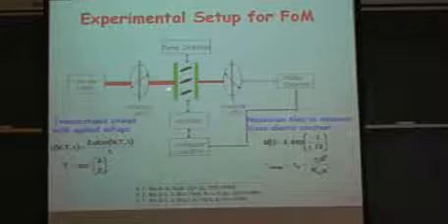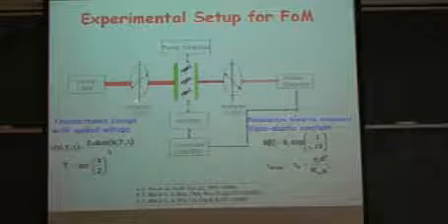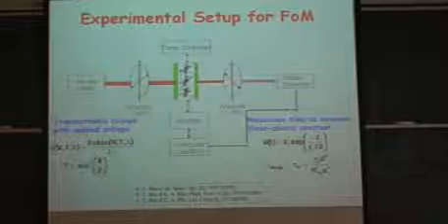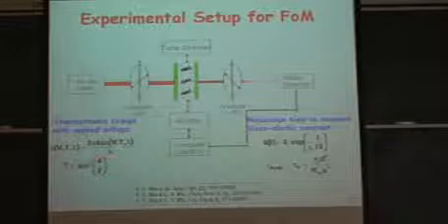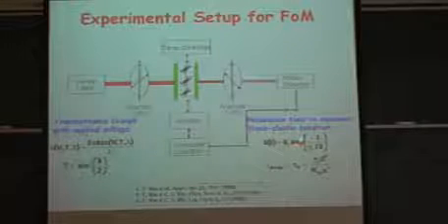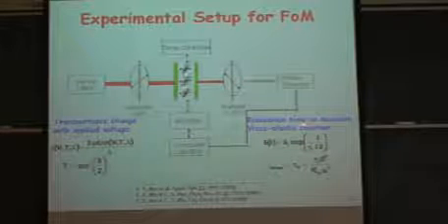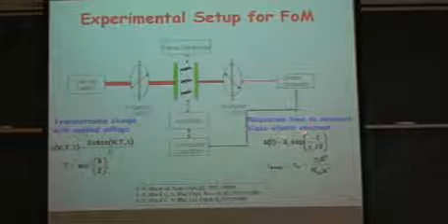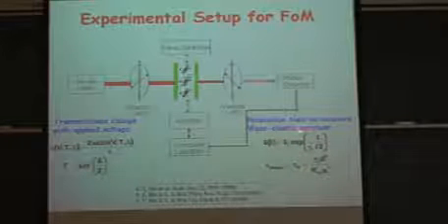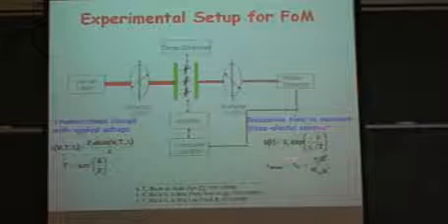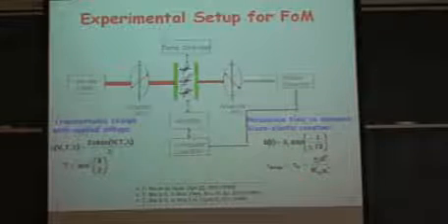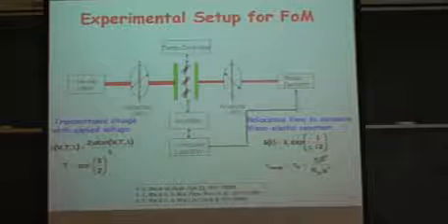In this setup, the polarizer orientation is at 45 degrees with the rubbing direction of the liquid crystal cell. In liquid crystal books, you can find this derivation: how to get this equation with this setup. Okay. So then we also measure its dynamic property. We measure the relaxation time at a controlled phase retardation. For example, we bias the voltage at 1 pi. Then we remove the voltage, get a relaxation curve, fit this exponential equation and get tau zero. So we get the viscoelastic constant.